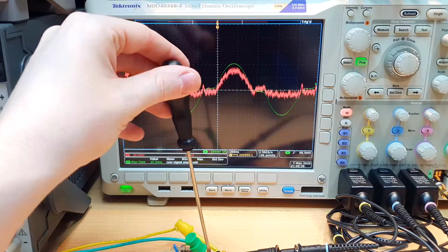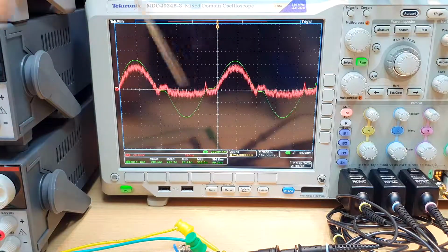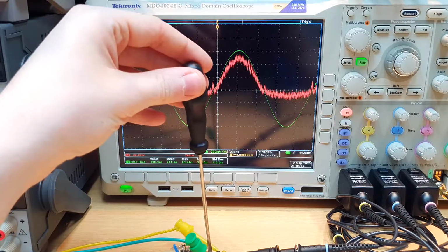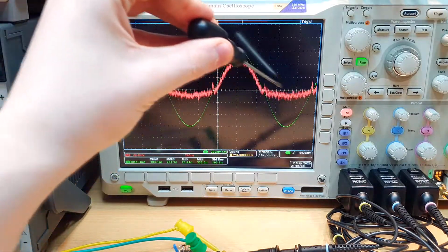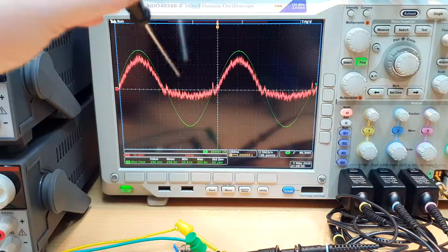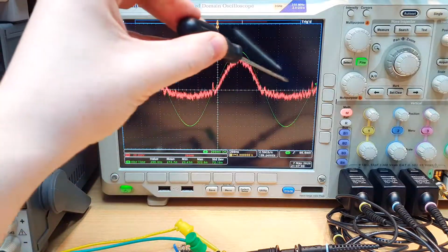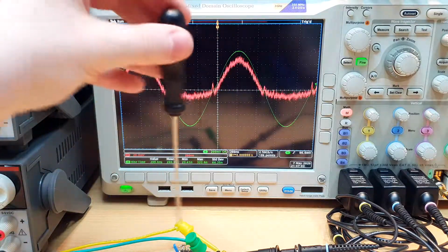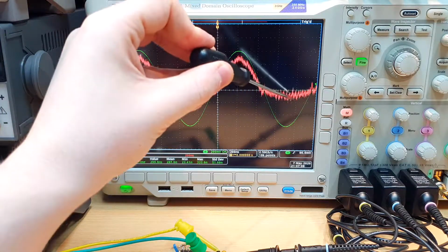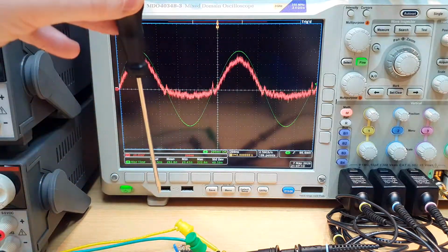Now we do not have enough biasing to get the voltage to follow correctly. We can see that we have kind of a negative current. This is because of the junction capacitance, which is sourcing a little current on the negative cycle when the junction is discharged through the resistor. So here the transistor is turned off, but the junction capacitance is sourcing a little bit of current.